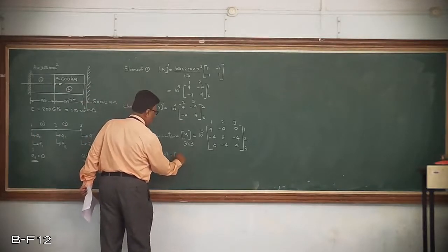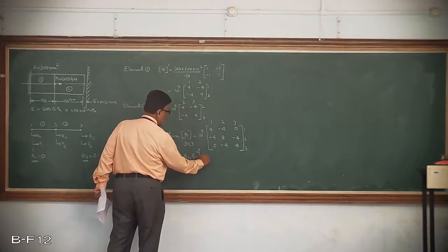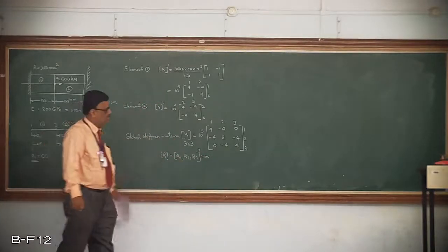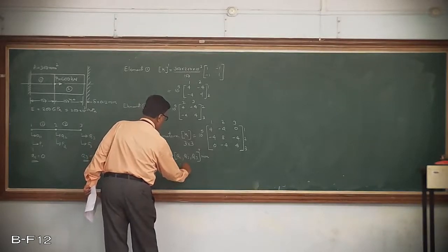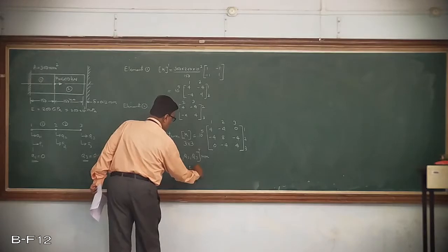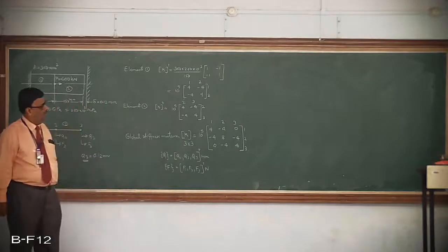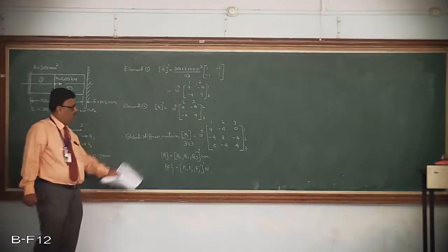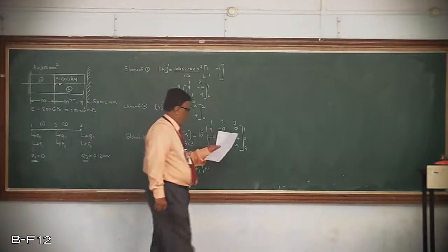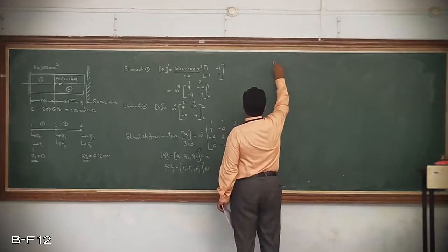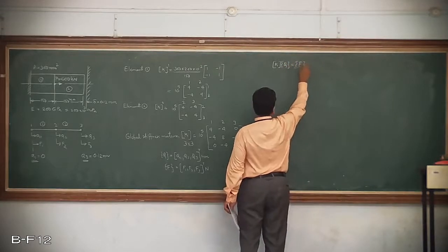As far as the force vector, or of course Q, is concerned, if I write it in the row form, it will be Q1, Q2, Q3 with the transpose, because I need to write it in the column form. Similarly, the F is going to be F1, F2, F3 transpose, in Newton. So this is the global stiffness matrix, then the global nodal displacement vector, and the global force vector. We are going to write that. And once we write the FEM equation, KQ is equal to F, we need to write that.